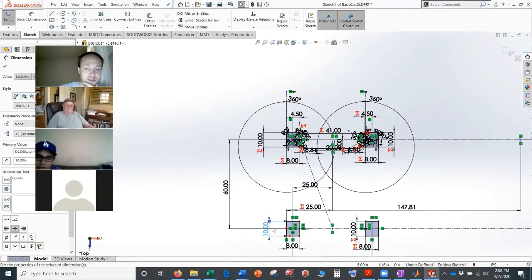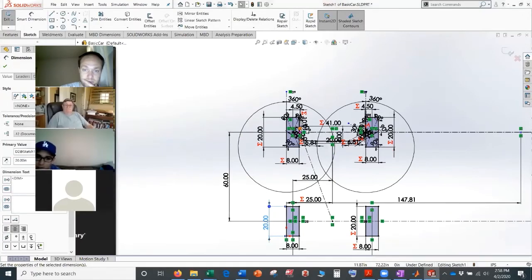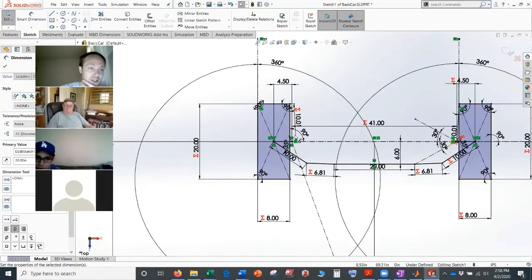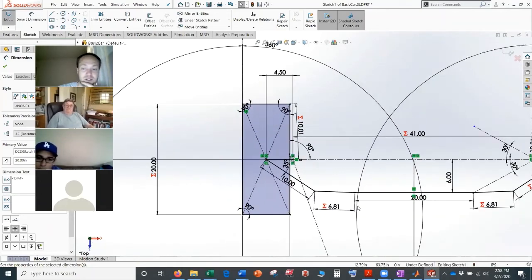Could you change the distance from the center of your tire to that distance? Can you make it off center, forward and back, the steering axis? Yeah, we could. I didn't program that in yet in this model. Or like for caster, I guess. Yeah, you could have caster with this as your average steering, but you might want to move it off. For example, I need to fix the distance from here to the front and the distance here to here, so it rotates the tires.